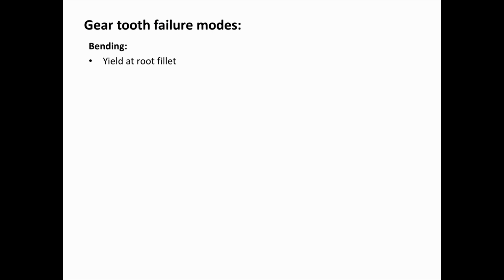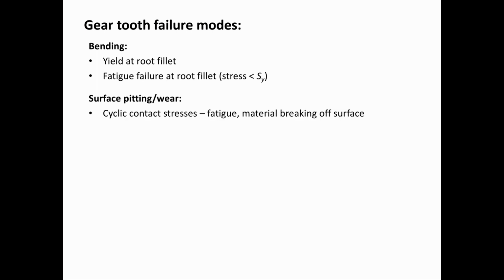Due to bending, we need to pay attention to yield at the root fillet and also fatigue failure at the root fillet, which could occur at stress values much lower than yield strength. And at the contact surface, we should pay attention to surface pitting and wear, and this is primarily due to cyclic contact stresses and fatigue and material breaking off the surface.